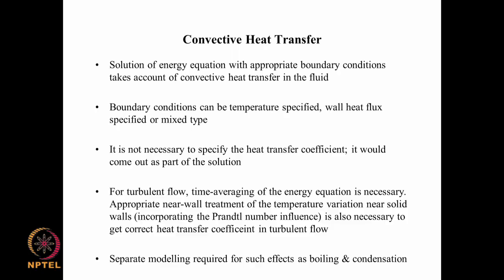In the same way here, if you specify the wall boundary conditions and the flow rate and those kinds of things, then you will be able to get a temperature distribution and the corresponding heat flux through the walls, and from the heat flux through the walls, the wall temperature and the ambient temperature, you would be able to get a heat transfer coefficient if you wanted. So, the heat transfer coefficient need not be specified here. The convective heat transfer coefficient is already taken care of, and it is nowhere explicitly calculated unless you want to have it.